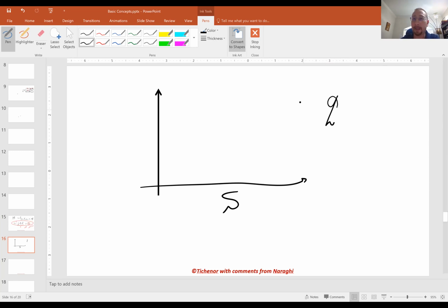L was Q, S, CL. I change the surface area, but I keep CL the same. So the angle of attack is not changing. The size is changing, but the shape is not changing. The airfoil is not changing.